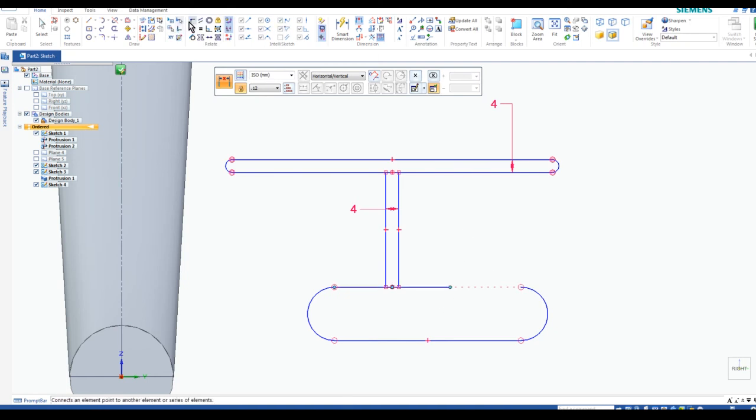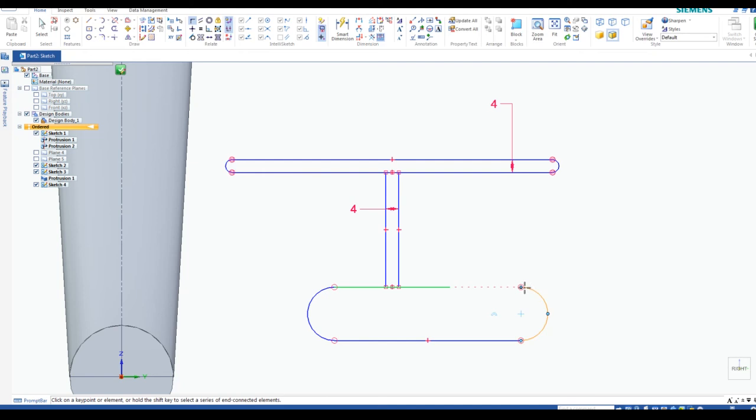Here I have to reconnect it because it disconnected it, just like that. And do the same thing here. And this is, again, the main reason why I like using the opposite side. There. Okay, so now I have that. This has to be the same thickness as this. So probably the easiest way of doing it is if I go equals, I select that, and then I select this, and it makes it equal. Because they're all interconnected, right?